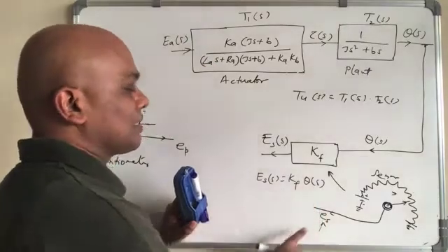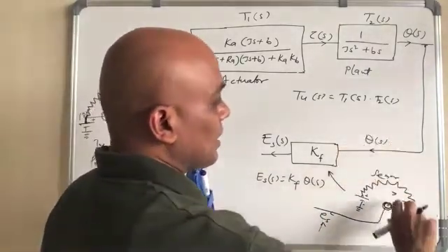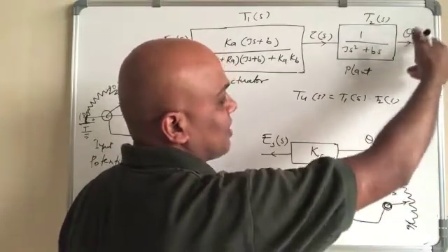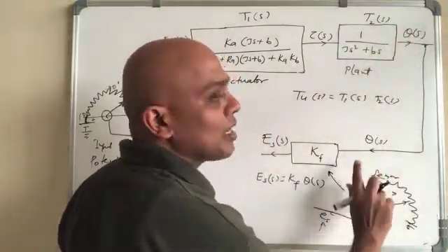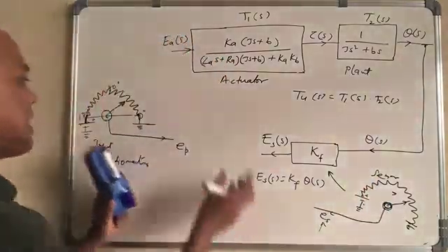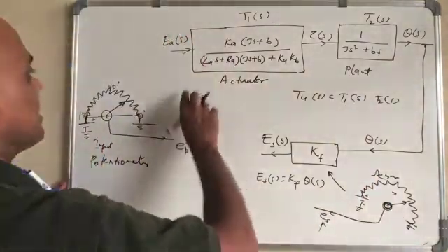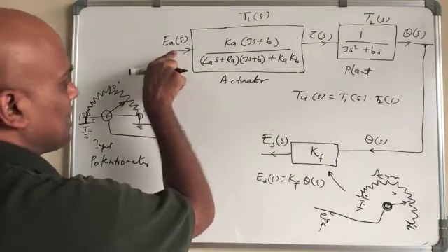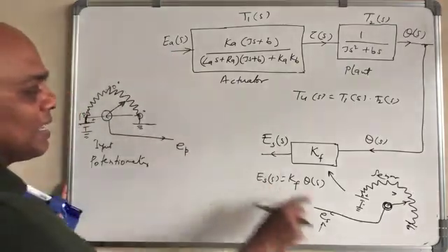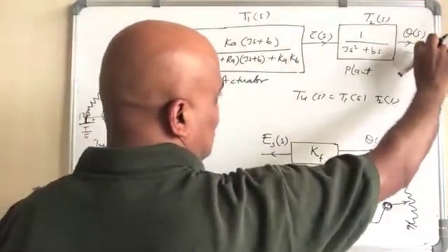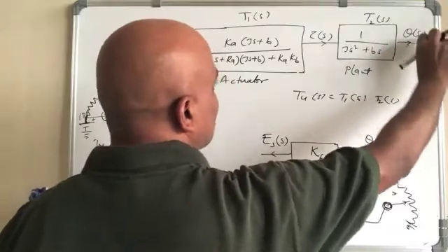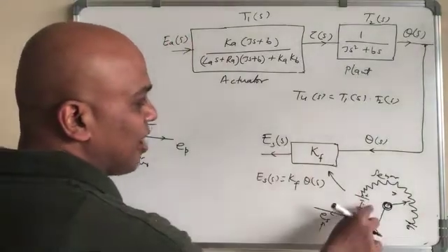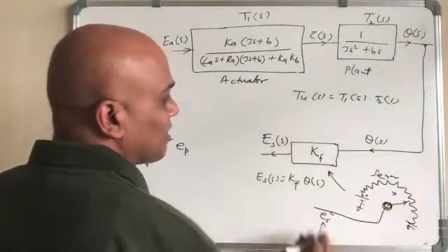So this is measuring. Theta is the physical quantity, the mechanical quantity, and finally we have to convert it into a voltage, so that we can play with it, so that we can control it, because here the input is voltage only. Hence the sensor will just sense where the position is, and that position will be converted into the voltage. And how? This is the mechanism by which you convert it.